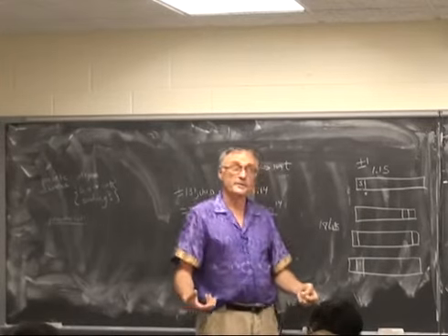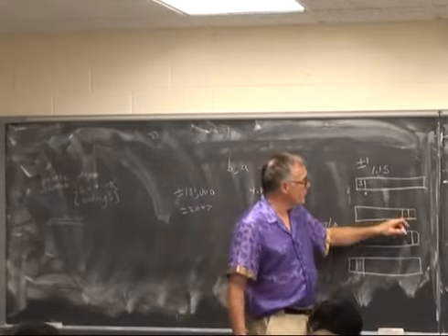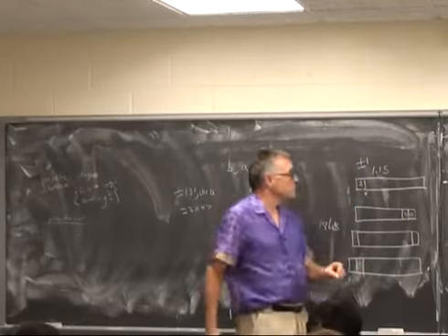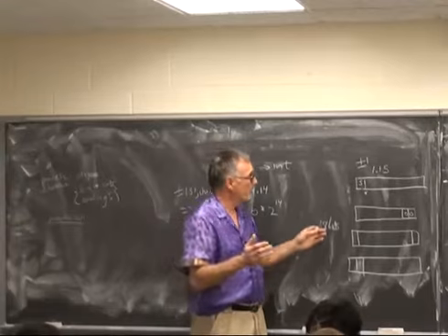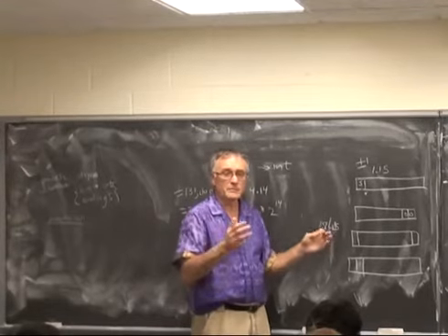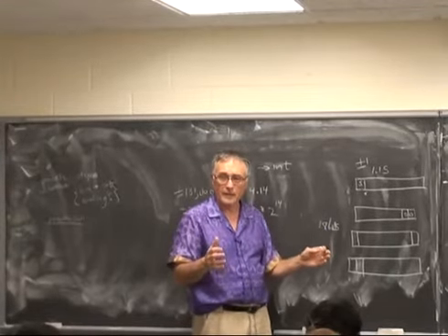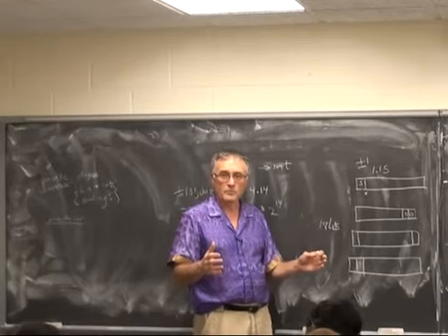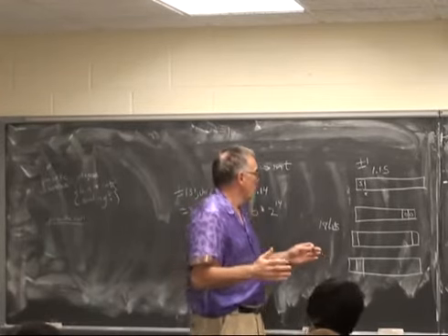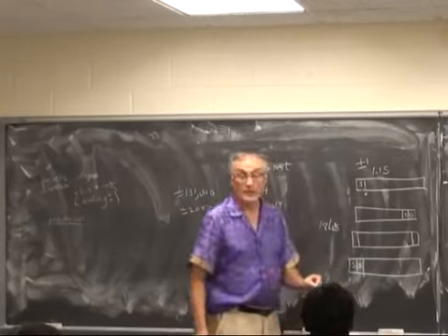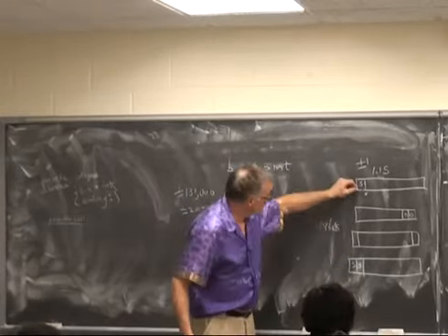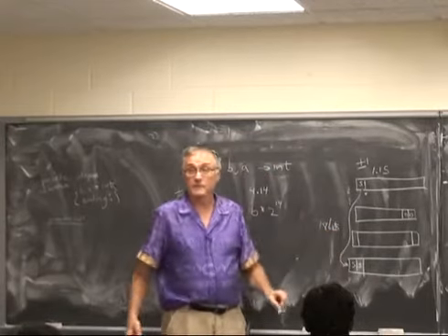The trade-offs. If you make 2 zeros here, then you've maintained as much precision as you possibly can at the risk of overflow. If you put 2 sign bits here, you have to copy the sign bit from here into the top 2 bits, obviously.